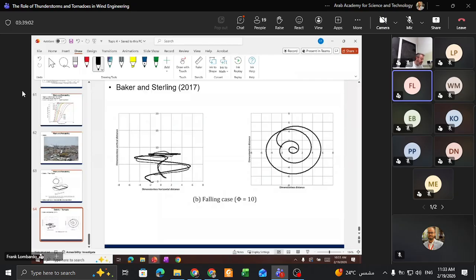So you can follow it through space. And then here's the plan view from the top down. You can see here that it gets generated probably close to the tornado and then spirals its way out, centrifuged out from the center of the tornado and ends up close to back where it started. This gives you an idea of a particular trajectory that you can develop from these models. The difference here is it's a tornado wind field model. The other ones assume that the speed doesn't vary over some considerable distance, for example, and the direction doesn't either.